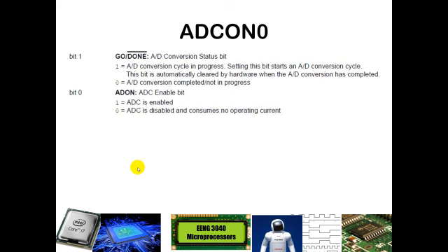But if you are needing that, it is very important that one of the first things you do is power on the ADC module. It is also important that you use this go bit when you have everything set up and are ready to go ahead and initiate the analog to digital conversion. We will talk about later, you don't want to do it all in one fell swoop. You will want to set up the channel first, and then once all of that is set up, then you will initiate the analog to digital conversion.